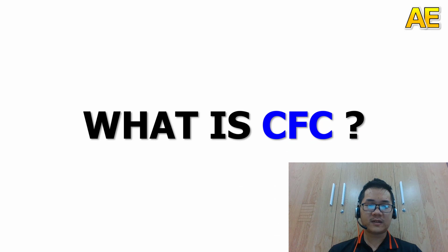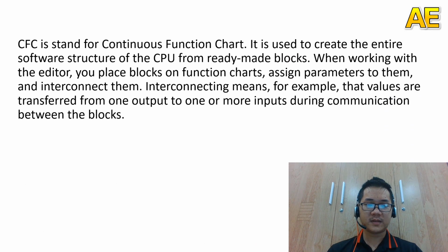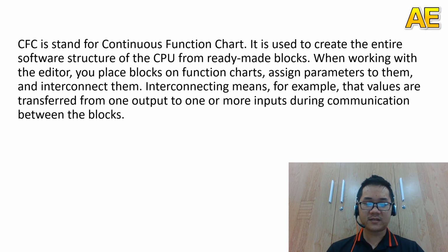Firstly, what is the function of the CFC? CFC stands for Continuous Function Chart. It's used to create the entire software structure of the CPU from ready-made blocks. When working with the editor, you place blocks on the function chart, assign parameters to them, and interconnect them.